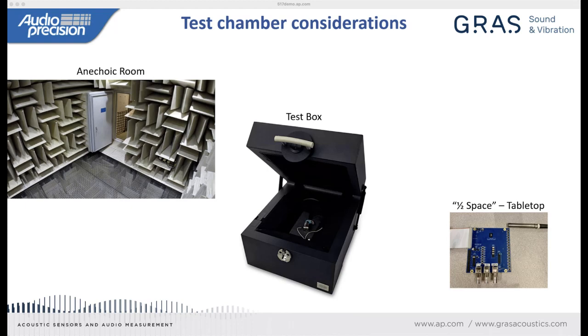And in this case, what it means is the reflections from the tabletop itself occur at exactly the same time as the primary signal. And so I sort of don't see them. I don't get a diffraction effect, if you will. And I'm going to use an analog measurement mic that's aligned fairly close with the number 1 microphone in the array.